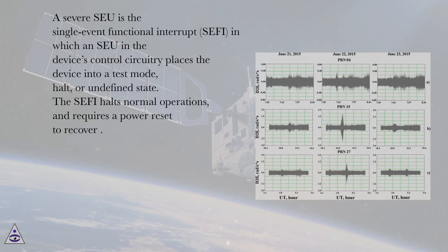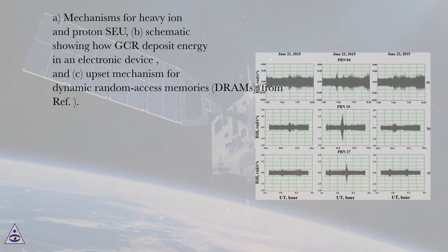A severe SEU is the single event functional interrupt, SEFI, in which an SEU in the device's control circuitry places the device into a test mode, halt, or undefined state. The SEFI halts normal operations, and requires a power reset to recover. A. Mechanisms for heavy ion and proton SEU. B. Schematic showing how GCR deposit energy in an electronic device, and C. Upset mechanism for dynamic random access memories, DRAMs, from Ref.